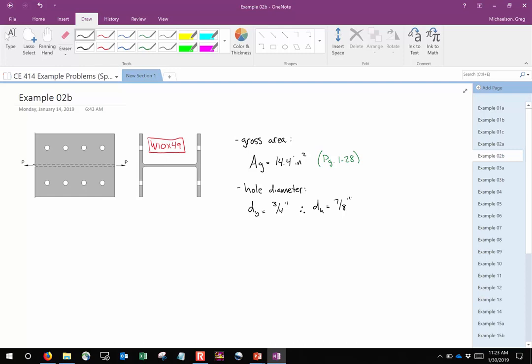I'm getting what she was saying, that it's the flange, that you're using T sub F. And you're using 0.56 because that's the decimal value, not the drafting value. We don't use the fractional values for design computations. So what we'll need for net area is we'll need 0.56 inches, again from that same table.